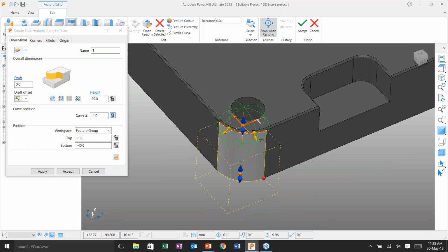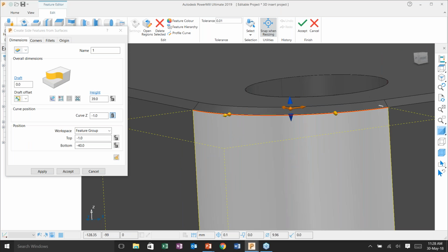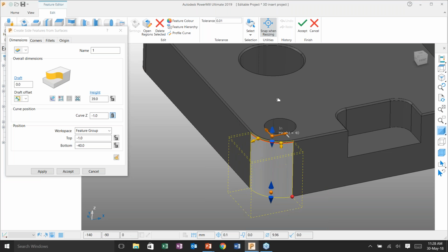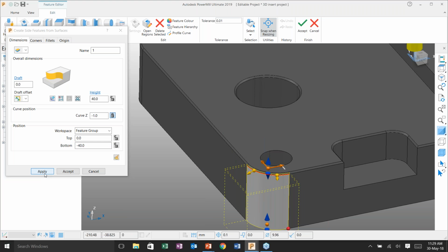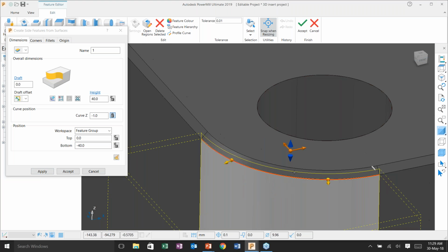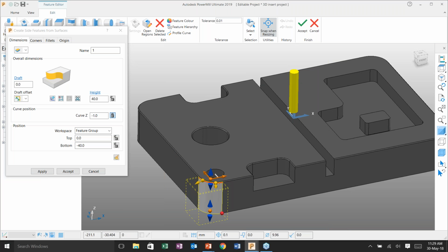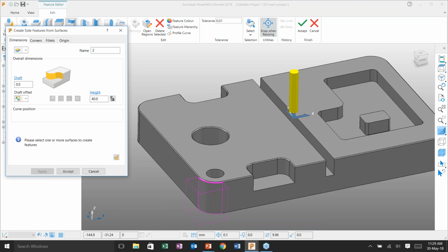Now, if you see this, it extracted until the chamfer end. So what you have to do is just drag this arrow mark and place it over the top surface. I'm not going to impose chamfer within the fillet because I'm going to create the chamfer all around, so I just leave it as it is.